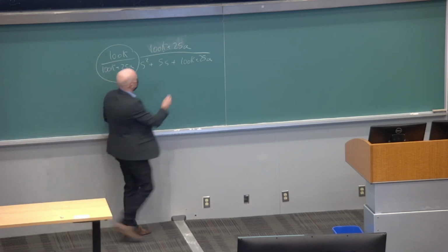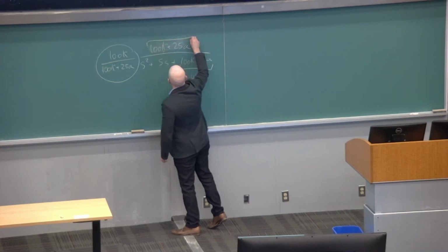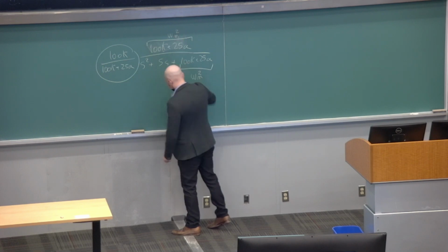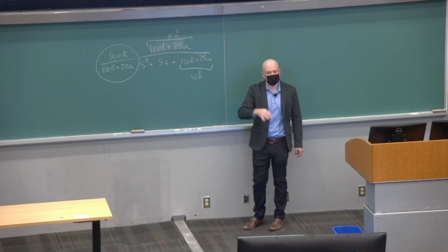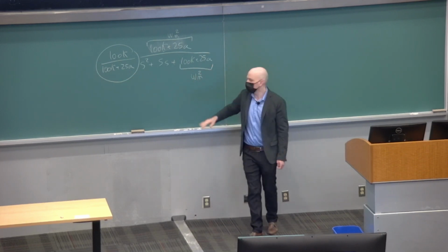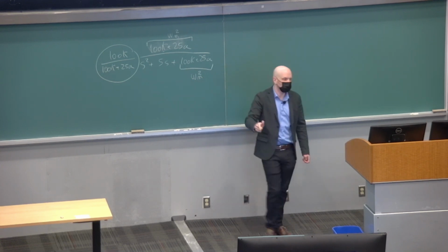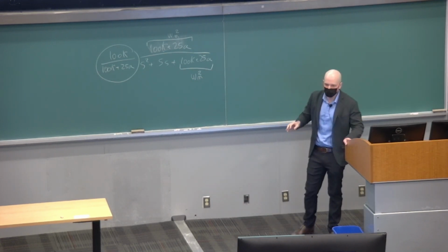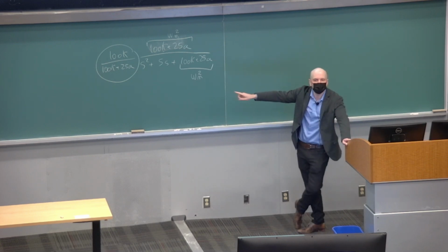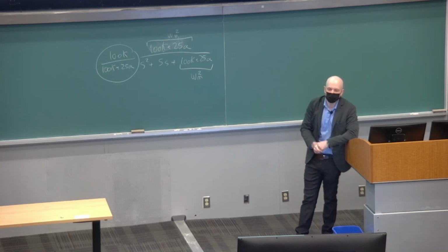So now I have omega n squared here. And also I have omega n squared here. They are the same. The only difference compared to where we started from is that we have this in front of it. It's just a scaling factor. The transfer function itself doesn't change shape, doesn't change the percent overshoot, doesn't change the damping ratio. That's all the same, but we just added that in front of it. And then the whole thing may have a different final value, but it will not change in shape. Does that make sense? Yeah?